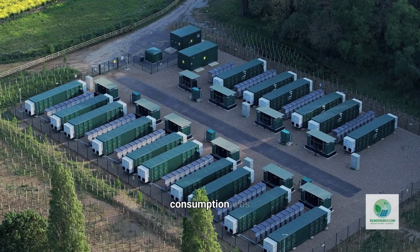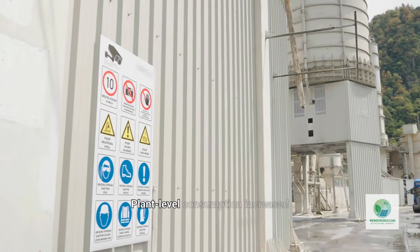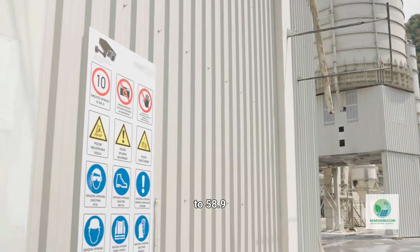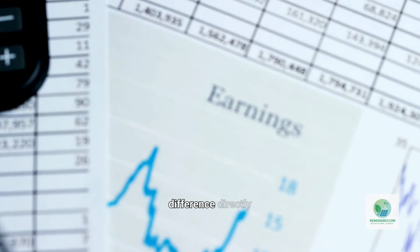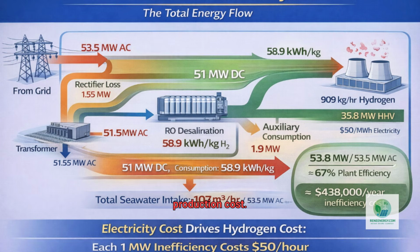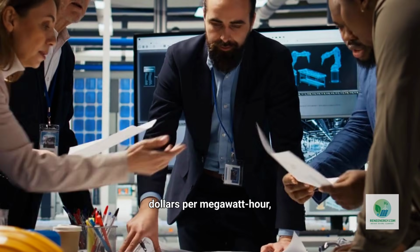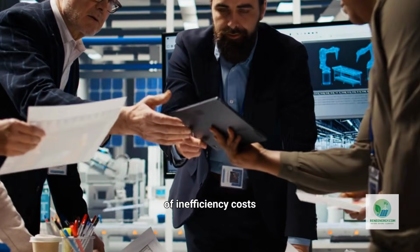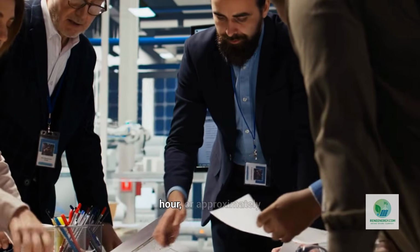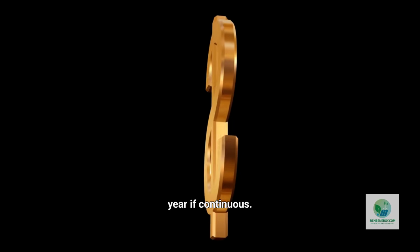Stack level consumption was 55 kilowatt hours per kilogram. Plant level consumption increased to 58.9 kilowatt hours per kilogram. That difference directly affects hydrogen production cost. At an electricity price of $50 per megawatt hour, each additional megawatt of inefficiency costs $50 per hour, or approximately $438,000 per year of continuous operation.